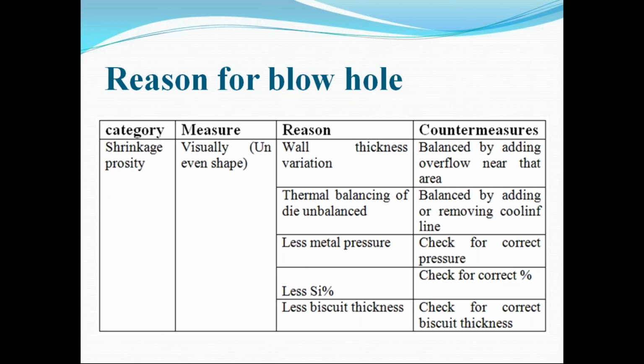Okay, so that's why this thing is very much important. This intensification is only effective on shrinkage porosity. Okay, this is one important thing. This is effective on the shrinkage porosity, and it cannot eliminate the porosity defect related to gas. Okay, this is only effective on the shrinkage porosity.